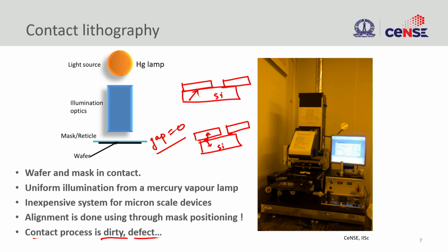So we should make sure that there is no particle between these two surfaces, so clean the surface properly. And just for clarity, this is silicon, you will always have some photoresist. Good. So the technique is pretty straightforward, but you should be careful about the surface contamination and how you are going to handle any contamination.